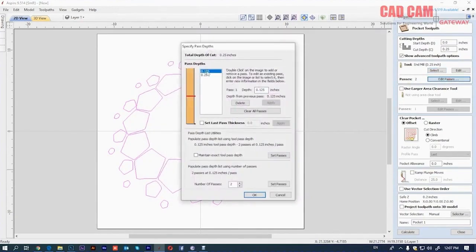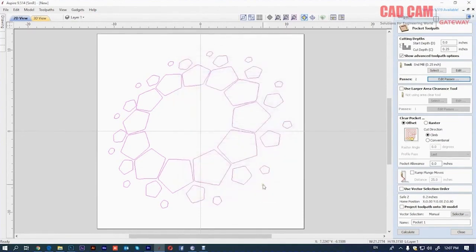Basically, what are passes? They are the steps in which you will cut the job with a thickness of 0.25, and each step is called a pass. I want to do it in one pass here because we are generally using soft materials like MDF or softwood. However, when working with blackwood or slightly harder materials, we need to use multiple passes. So I did it here with a single pass.